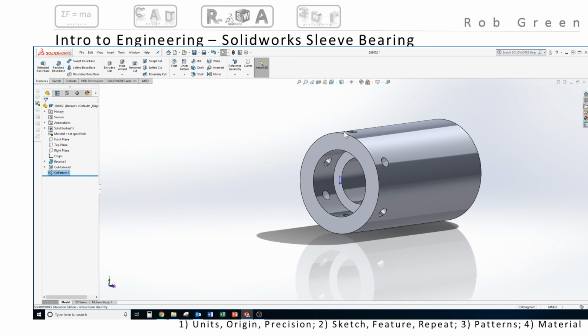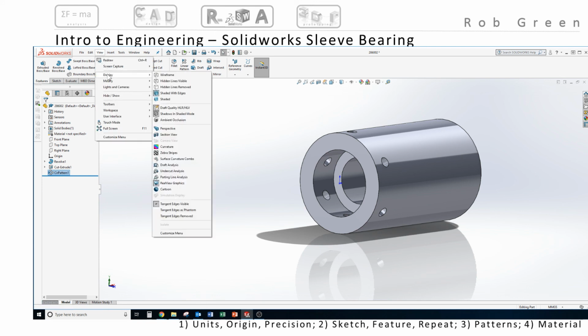And what's going to make sense to our eyes and brains is if these lines actually converge a little bit. And Solidworks has a display style that allows them to converge and have something that looks visually correct. So there's this option under View and Display, and if I move to the right and scroll down this flyout, I have this thing called Perspective.